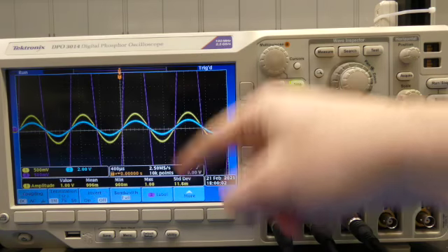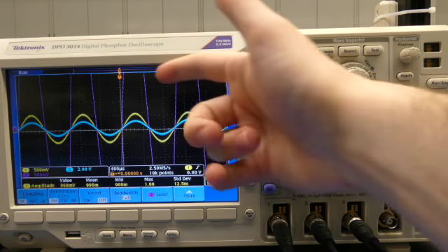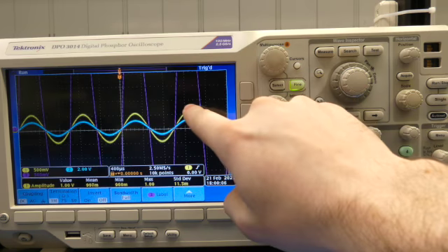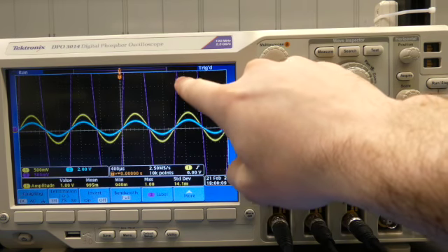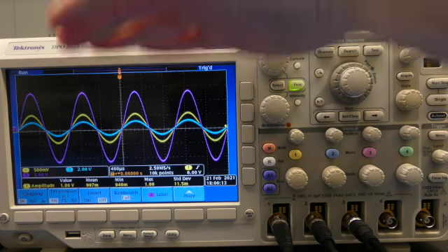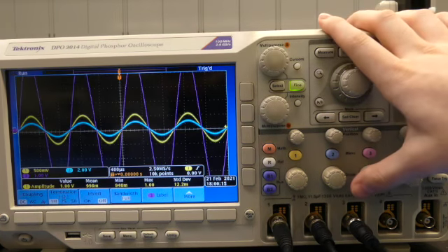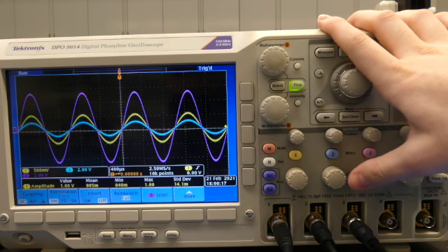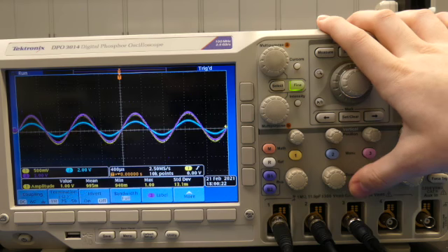You don't want it to clip at the bottom or the top. If it's clipped off at the bottom or the top, we know that the top of the waveform is way up here, but we can't see it in the picture of the oscilloscope. And if you don't have the picture of the oscilloscope, then it's not being measured. So your amplitude value is going to be off. I'll show you how to measure stuff in a second.